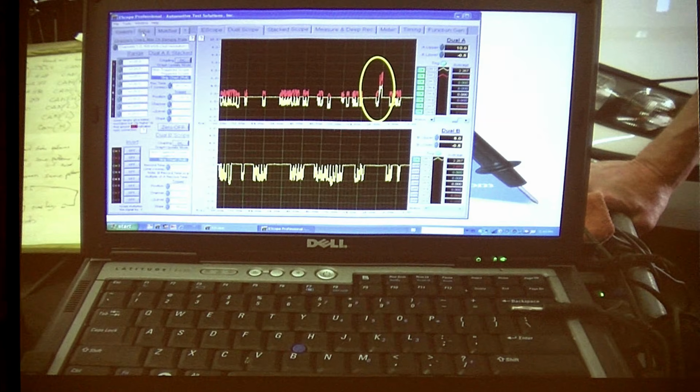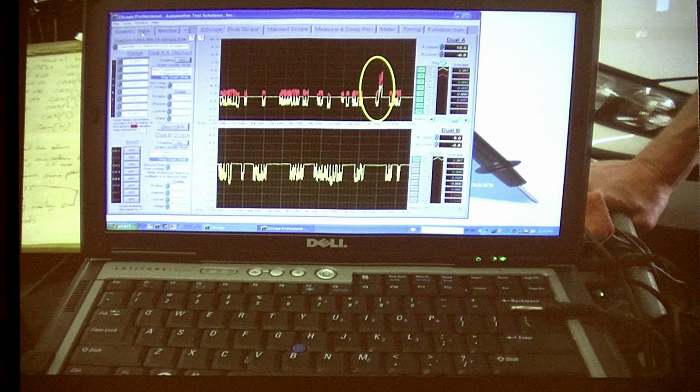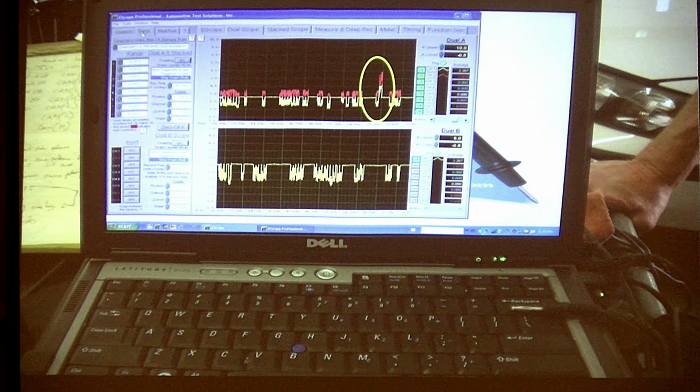We make a 100 meg scope and I make a 50 meg scope. And I don't use either of them on this stuff. On this car, I had my 100 meg scope, and what it does is go through data and then it catches it, and then you sort of look through it. Well, every time for 20 minutes, I never saw that fail on my high-speed scope, because that's the missing data. Remember, I load a buffer, and if I'm working at really fast speeds, I overload the buffers really quickly. That means I drop the data. So every time that was failing, that wasn't when I got my data. And then I would catch another bunch, and that wouldn't be when I got the data either, because it only happened once every couple of minutes or so.